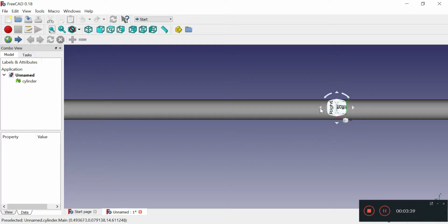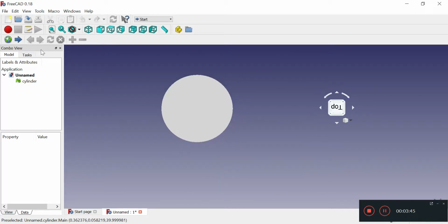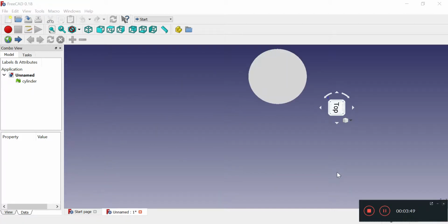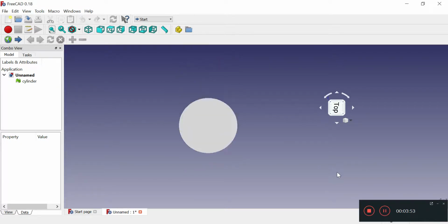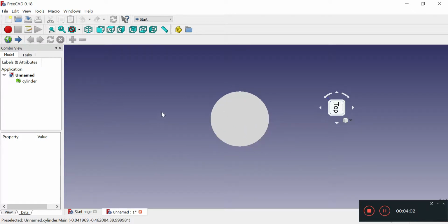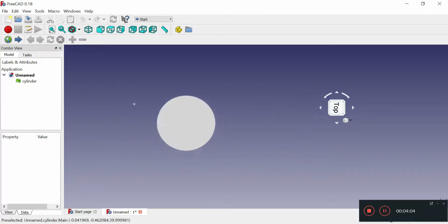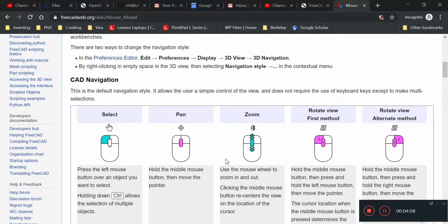It's not exactly like ParaView. This is the pipe geometry. You can zoom in and zoom out, and use your arrow keys to shift around and see the shape. If you want to drag it around, you press the middle mouse button, the scroll wheel button, and drag it around.